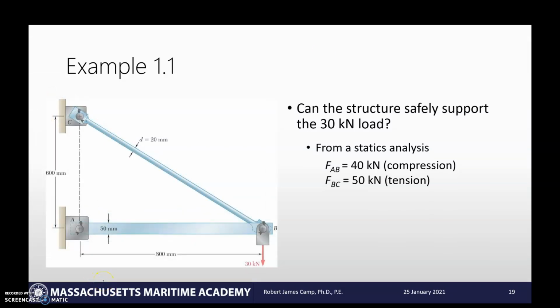Okay, we've got the right color. The first thing is we have to look at the material. Let's say we're going to use some kind of steel, so SKS steel, and we will say that it has an allowable stress of 165 megapascals. What does allowable mean? That means that if we go above that 165 megapascals, the system will fail.